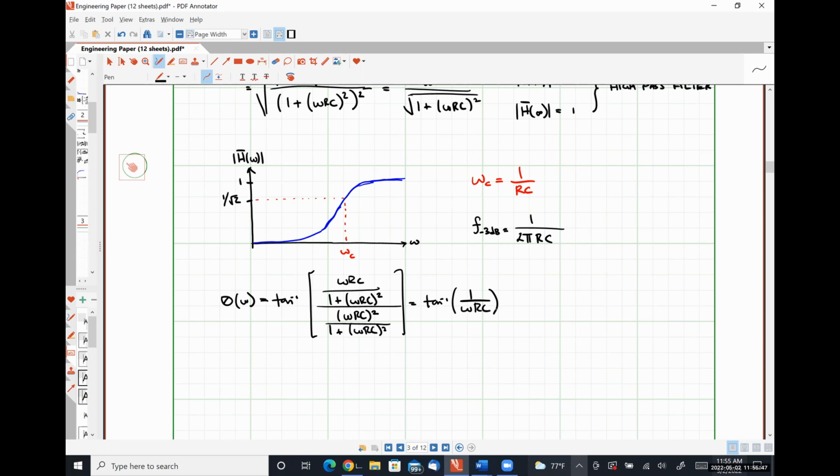Okay, so we have developed our methodology for analyzing these circuits, determining their transfer function first, and then using the transfer function to give us the magnitude response and the phase response. What we are going to do on Wednesday is introduce a second energy storage element and see how that meshes. So here's how we realize a low pass filter and a high pass filter. On Wednesday, we're going to talk about the realization of a band pass filter and a band stop filter, and